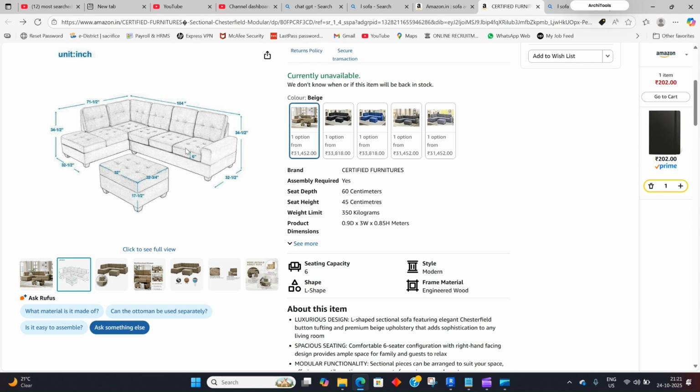First of all, you can see that the base for each seat as well as the backrest is a common thing. So what we can do is we can provide a separate family for this and for the backrest too, and we'll nest it all together in a new family. So first of all, we'll be modeling this part.